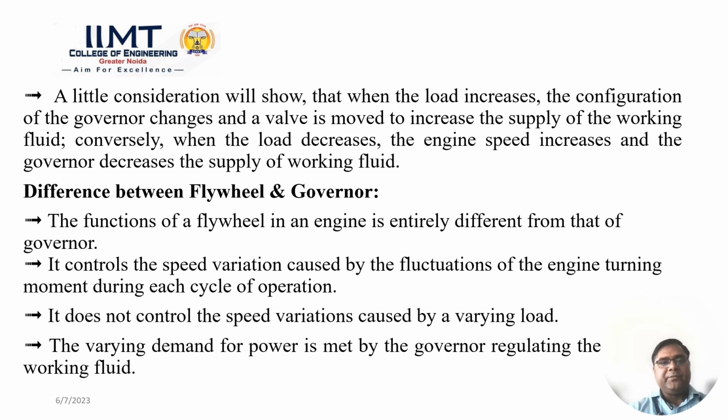The function of the flywheel in the engine is entirely different from that of the governor. It controls the engine speed variation caused by the fluctuation of the engine turning moment during each cycle of operation. It does not control the speed variation caused by the varying load, and the varying demand of power is met by the governor, regulating the working fluid.